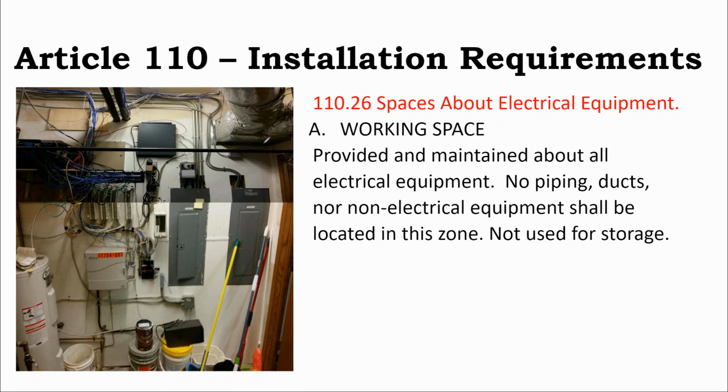At first glance, it could seem like this air conditioner is sharing the same spot as the electric service panel, but it's actually not. There's a 6.5 foot dedicated space vertically for your electrical equipment from the floor, or from wherever it starts. And so 6.5 feet up, aside from how some of this data cabling looks, the code violation of this room is actually the buckets that could be easily moved.